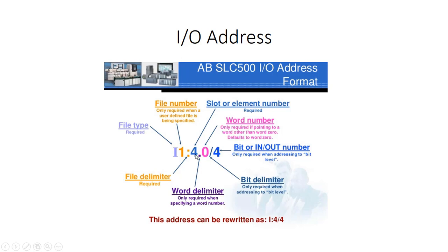Then on the 4th screw terminal down, I run the wire to a push button. So once again, I have a push button wired into screw number 4 on a card that's in slot number 4, and it's an input card. So that is the address that gets used.